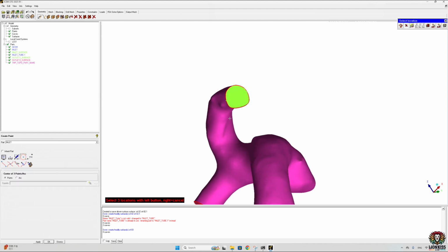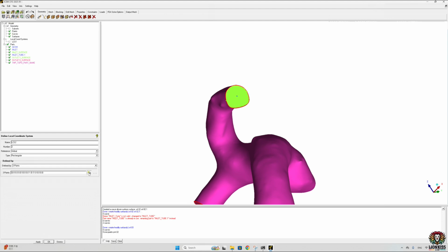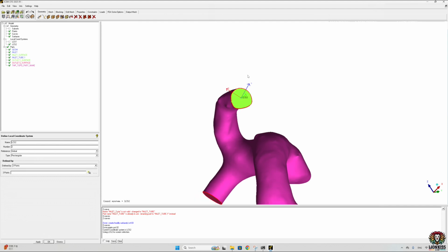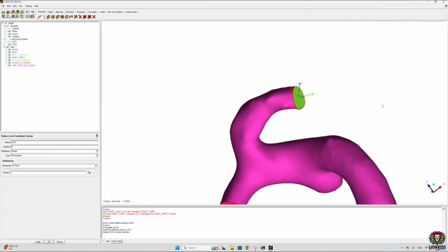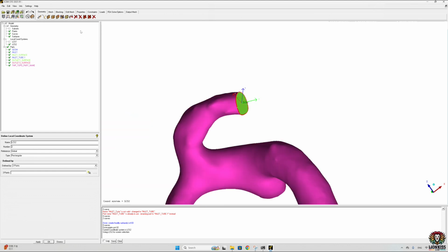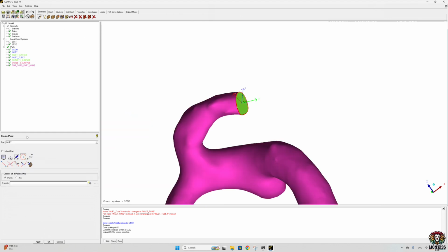So same process, 1 2 3, make a middle line and make the coordinate system, go 1 2 3, and click the middle button. Go and XYZ. Okay, just for example 20 mm, so apply. So you can see we get our point 20 millimeters away.